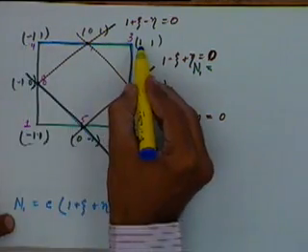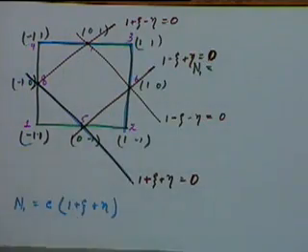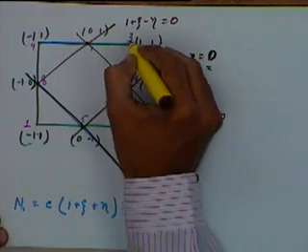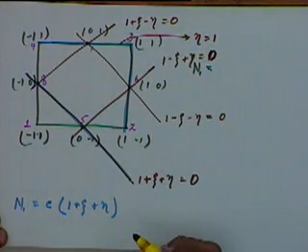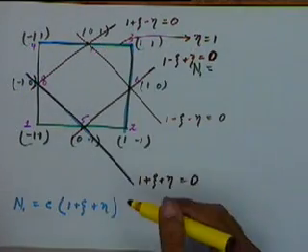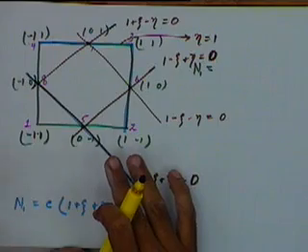The equation of this straight line, the top one, is eta equal to 1. Why don't we take this shape function to be simply Lagrange polynomials? Again, we can take these shape functions to be simply Lagrange polynomials. The shape function can be defined in any way. The choice is totally up to the user. You can take shape functions according to any formulation as long as they meet a particular set of conditions. We can take it this way, we can take it in any other way, there is no problem on that. The only thing that will change would be the stiffness matrix that you will get.